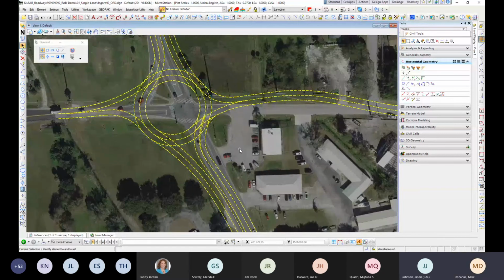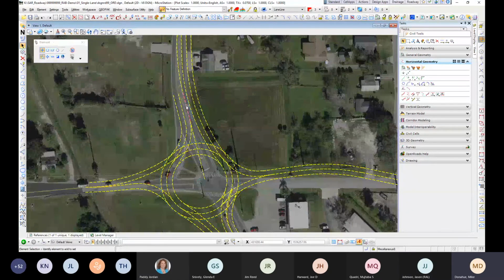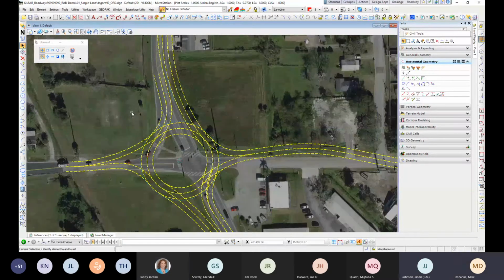I mean, it really depends on what your typical section is. So I have a 2-lane section here. And this lane may have a different cross slope than this outside lane, depending on my grades, right? And if you're in a curb and gutter facility, you have a longitudinal grade on that outside that you have to adhere to per criteria. So if 2% makes sense for this inside lane, but this has to warp over to a 3% at times to achieve the grade along your curb line that you need, then this template may need to have single lane flexibility from a cross slope perspective. Whereas this side, you may not need that. You may just be able to do one piece of pavement all the way across 24 feet wide. Just like you were saying, every intersection is different. So it depends on the scenario.